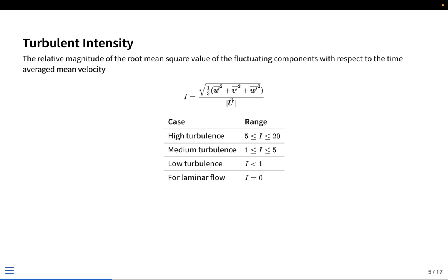So if you can measure the velocity as a function of time and then take an average value of it, you have a series of velocity measurements, you compute the mean value, you take the deviation, those fluctuations, and you can do the average in this particular fashion over time, and that will give you the turbulence intensity in that particular experiment. So in your similar experiments, you can measure the same value and quantify the turbulent intensity. And if these two experiments have the same values of turbulent intensity, then we can assume that, more or less, you are able to replicate the same experimental case that has been done by a different person.